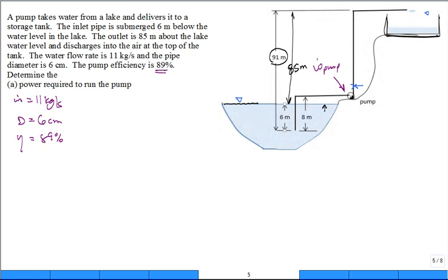All right, so how am I going to analyze this to get the power required to drive that pump? What do you think? Energy balance and a mass balance. The mass balance is pretty straightforward, but for an energy balance, let's introduce a control volume. In thermodynamics, we have a control volume, and when you take fluids, it'll be a Bernoulli's equation, but it's very, very similar. At the end of this chapter, I think it shows you the analogy between the Bernoulli's equation of fluid mechanics and the energy equation here for control volume.